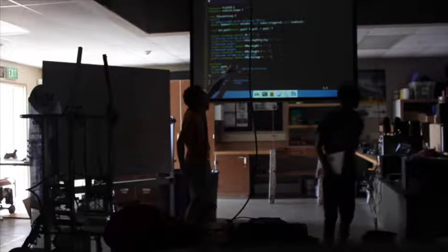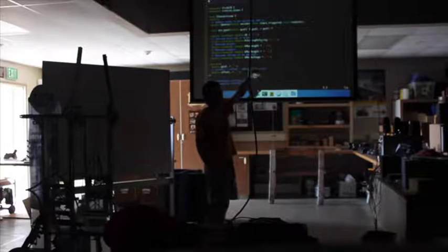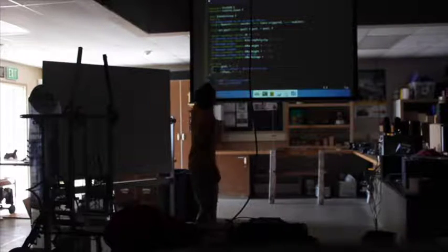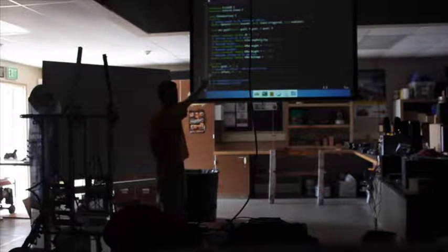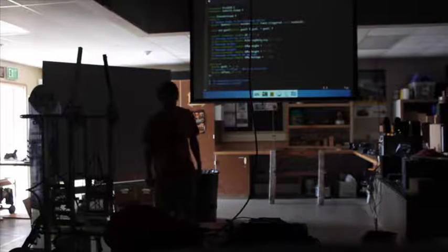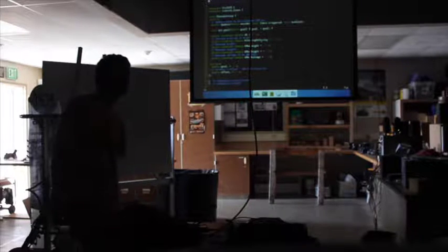So I'll start. I put together a skeleton just so that you don't have to watch me type up the skeleton. The idea here is we have an elevator control loop. It's our interface for our control loop. So we have an update function, which is going to take the current encoder value. We have a Hall effect sensor on this robot, so it tells us when the elevator is at a certain position. We're going to call this position 0. We need to define a coordinate system, so 0 is when the elevator is at the Hall effect sensor. And then it's going to take an enabled bit, so something from the field saying the robot's on or not. And then it's going to return a voltage, saying this is the voltage to command the motor. So it's a pretty straightforward interface, which we can actually implement a quick simulation for.